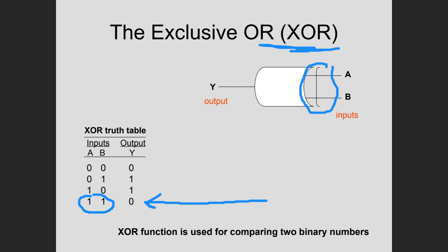And depending on the requirements for the system, the other system can also feed back a received signal okay. It also doesn't necessarily need to be hardwired. You can send the same kind of interlock over Ethernet or whatever communication network you're using. The only difference is if you're using a communication network, you typically need to send some kind of heartbeat message between them, so that you know that if the state's not changing, you haven't lost communication.